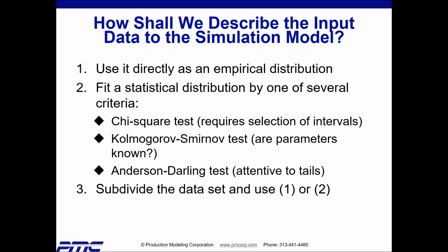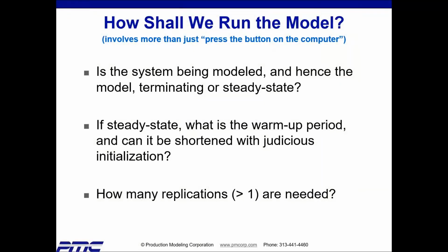Then I'd better subdivide my data set, and I also need to find out what percent of our production is model A versus model B, and I'd better know as the simulation runs, for each part arriving at the machine, is it an A or a B? So no, we don't just stuff the data into the model. Now, how shall we run the model? That's an input question. It's more than clicking a button.